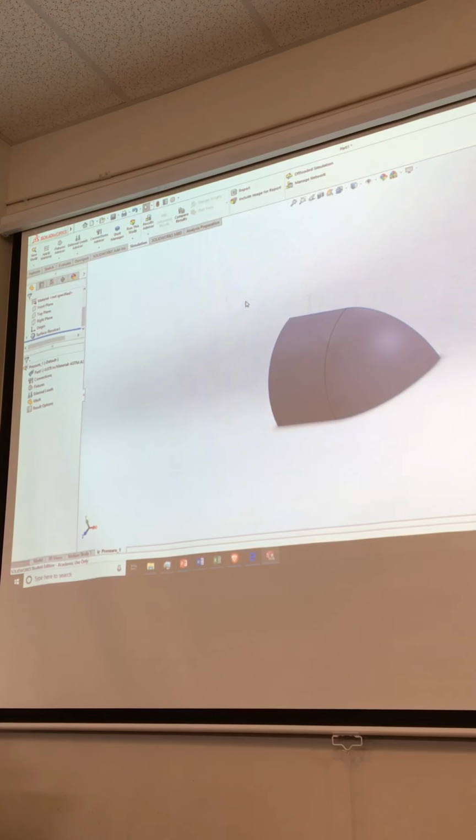Okay, I think that's big enough to support it. Typically, we say we can do thin shell analysis when it's over 10 to 1. Okay, well, I'm at 240 to 1. I think I can safely say that we're gonna get away with a thin shell analysis on this particular part. And that's usually true, because the materials we have are pretty strong, so it's usually the case.